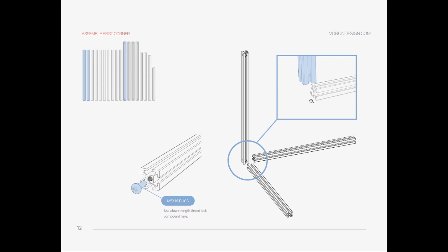But if you want to do it yourself, you need to be careful about the position for the drilling. So this hole needs to be drilled at the center when you think about the width, and there should be a 10 millimeter offset from the bottom or from the beginning.